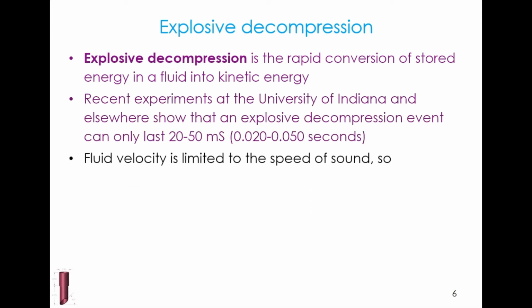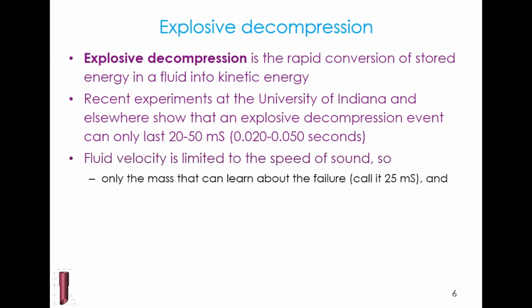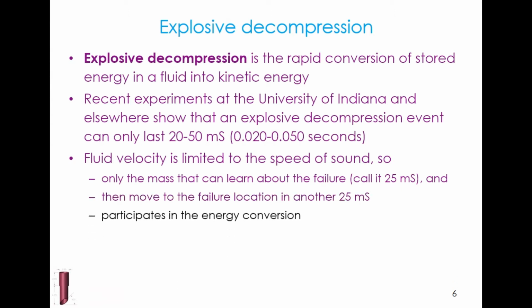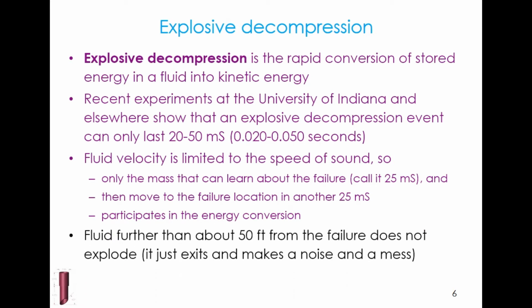Fluid velocity is limited to the speed of sound, so only the mass that can learn about the failure, call it 25 milliseconds, and then move to the failure location in another 25 milliseconds, can participate in the energy conversion. Fluid farther than about 50 feet from the failure doesn't explode. It just exits and makes a lot of noise and makes a mess, but it's not an explosion.